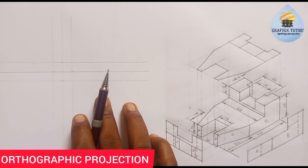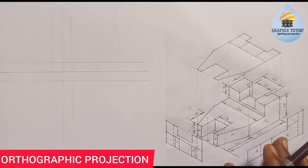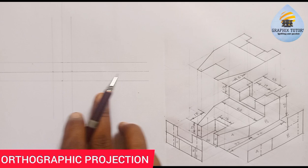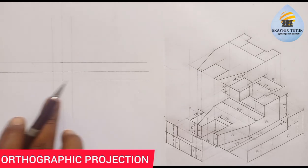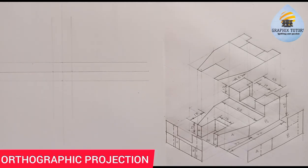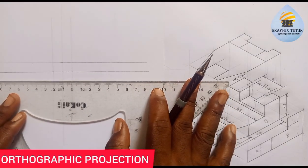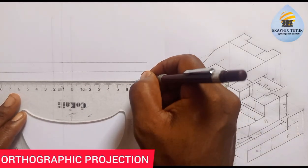Since I say orthographic projection, third angle projection, you place your front elevation at the fourth quadrant, either the fourth quadrant or the third quadrant. Any of these two you place your front elevation, you're on point, right? So since we're viewing it this way, let us draw here. So what is the entire length? The entire length from the beginning of here to here is given to be what? 70. So I'm going to measure 70, from 0 to 70. This is what we have here.